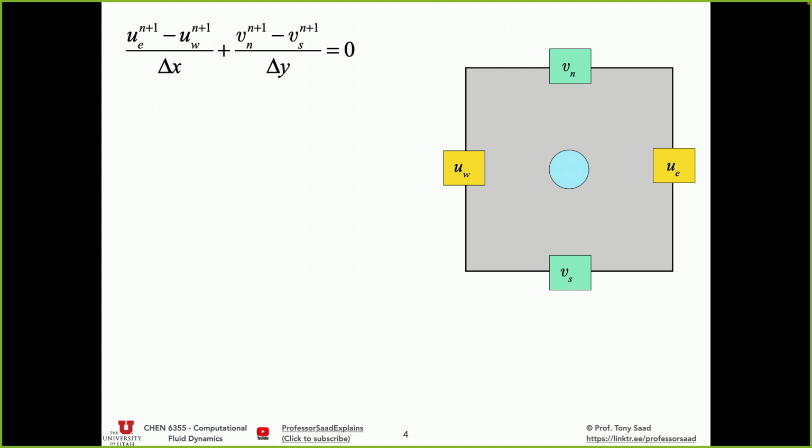Or you could say, well, at a control volume, the continuity equation sets the Navier-Stokes equations apart from all other advection diffusion equations, right? Advection diffusion has no conservation properties like the Navier-Stokes. They don't have an algebraic constraint on them. They're conserved in the sense that whatever is coming in is leaving. With momentum equations, you need to satisfy that algebraic constraint, div u equals 0. So in essence, this equation is very important.